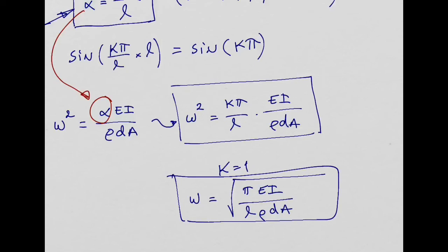This is usually the design frequency. You know, if you excite the beam with a frequency equal to the natural frequency, you get the resonance of the beam, right? You remember that from vibrations you did last year? You talk about resonance, right? So that's why the lowest natural frequency is a very important value to get in the design.